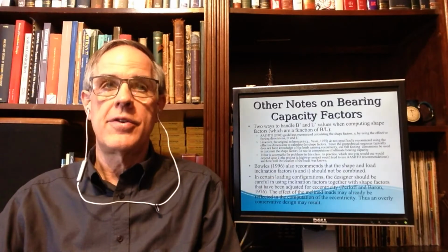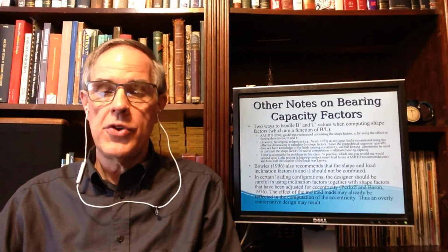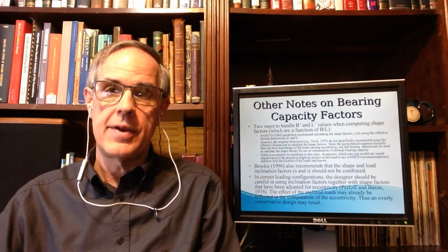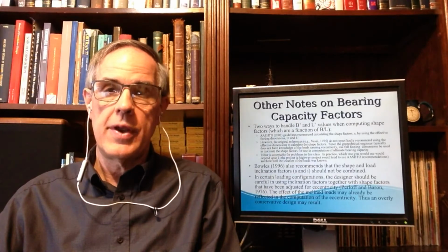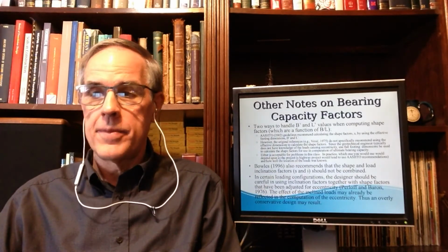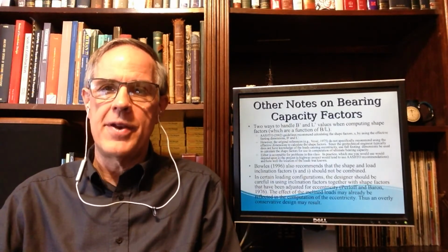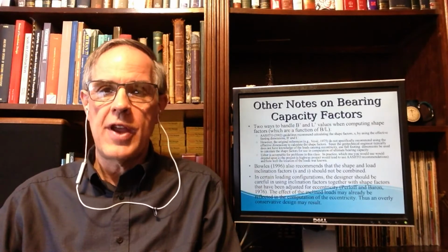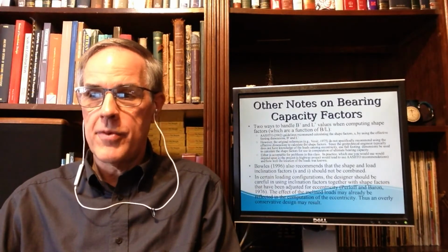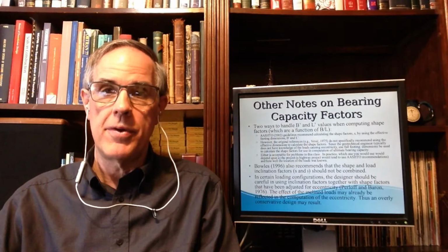In this class, either is acceptable, and which one you use depends upon what code and engineering practice environment you're working in. Another issue is combining shape and inclination factors. Some, like Bowles, have recommended not to do this, and you can be thankful that I didn't make you use Bowles for your textbook.